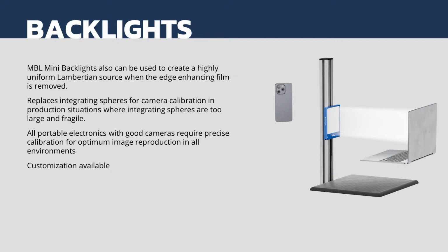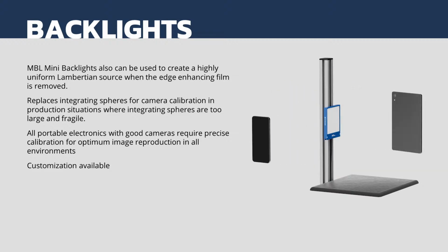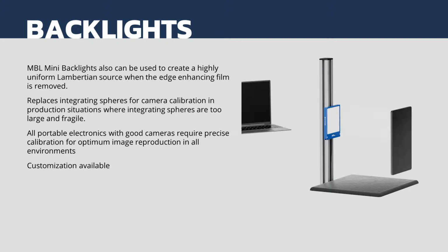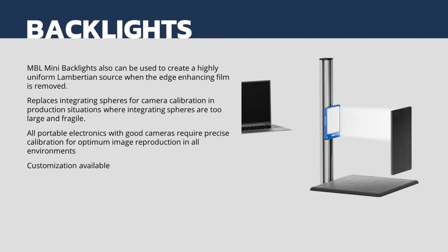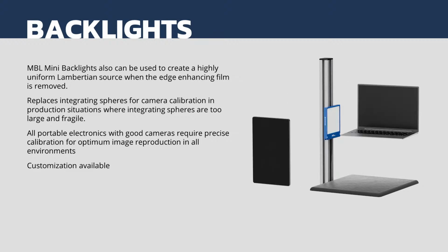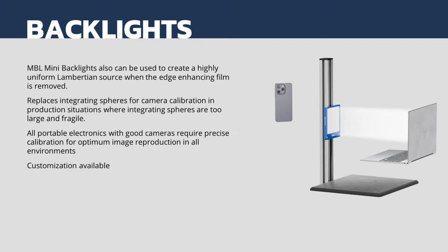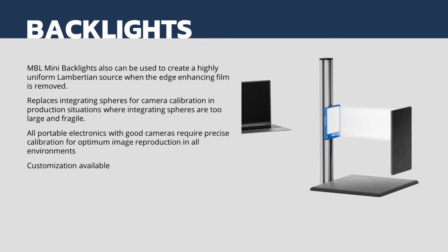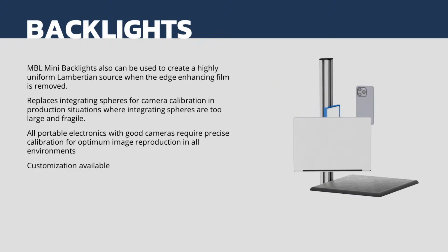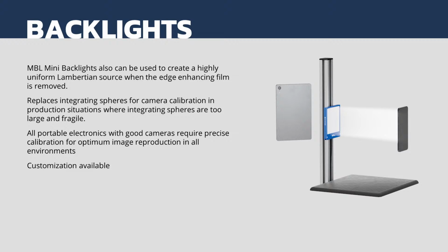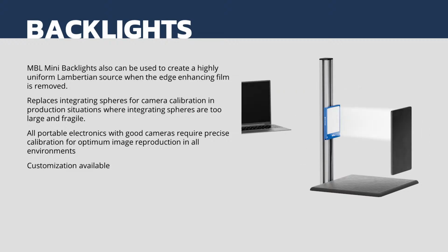And to get the magic that they get out of them, Samsung and Apple and the other vendors have to calibrate these to a very high level to make the imager that would otherwise be kind of poor perform really well. And they do that by calibrating and characterizing them. So to do this ideally in a lab setting, we would use what's called an integration sphere. It's kind of like a full 360 of the dome light we had there. It's a full sphere, with a hole for the camera and some photodiodes for precision measuring inside.